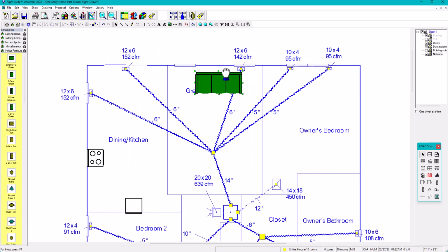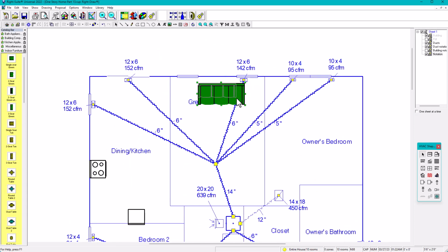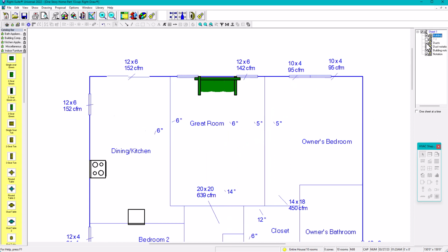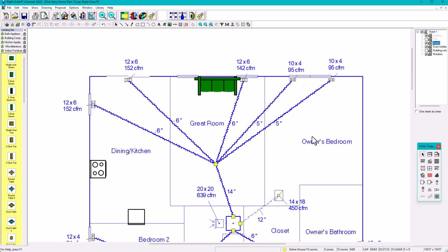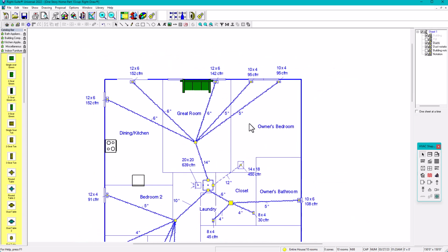Now what you can do in here is make it smaller. I'm gonna make it smaller, grab one corner and then put it there. And another option is that you can always move these names. So click in the room, hold shift, and then drag this name like this. That's very helpful. Okay, now again I'm gonna lock the building so that I don't affect it. Okay, so now my trick, check and uncheck, so that this is enabled. Okay, so now we have that, and then we're gonna go again for the bedroom.